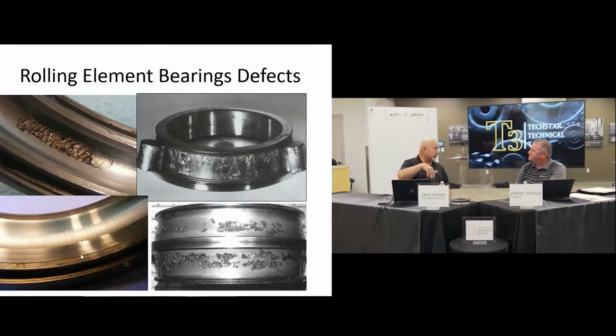So the balls on this one are doing this, but it's great because you've got lubrication there, right? Eventually, though, it pushes the grease out of the way, and it's metal to metal fatiguing. And you'll have a perfect defect of where the balls rolling elements were in the outer race. Or I guess maybe even the inner race too.